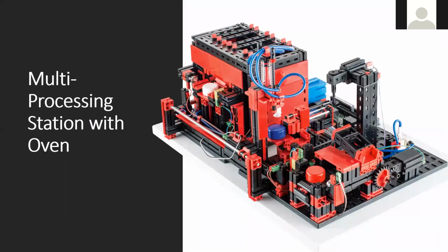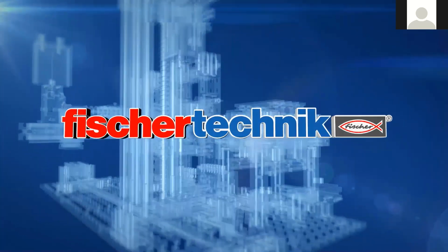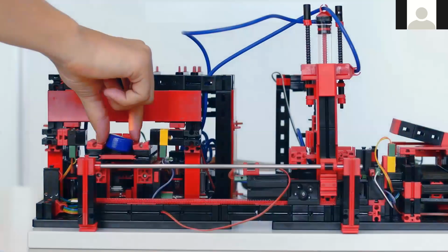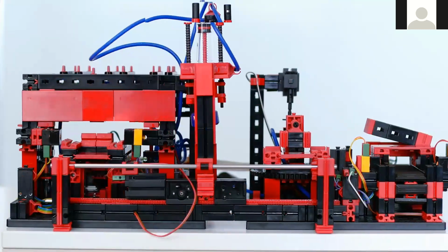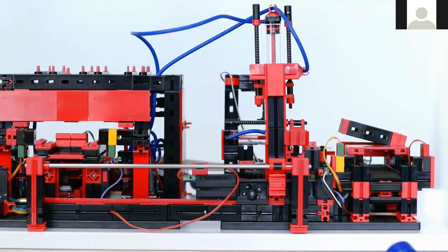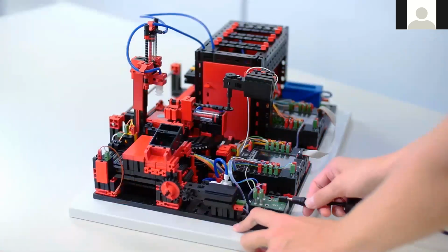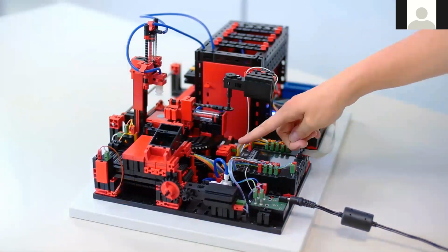The next model in the line is the multi-processing station with oven simulation. The model we'll see here features a furnace simulation with a pneumatic sliding door. There is a downstream processing station with a pneumatic transfer unit that includes a vacuum gripper, a cutter with a rotary table, and a conveyor belt. Components used on this model include 4 mini motors, 6 push-button limit switches, 2 photo transistors, 2 LED light barriers, 4 solenoid valves, and a compressor.